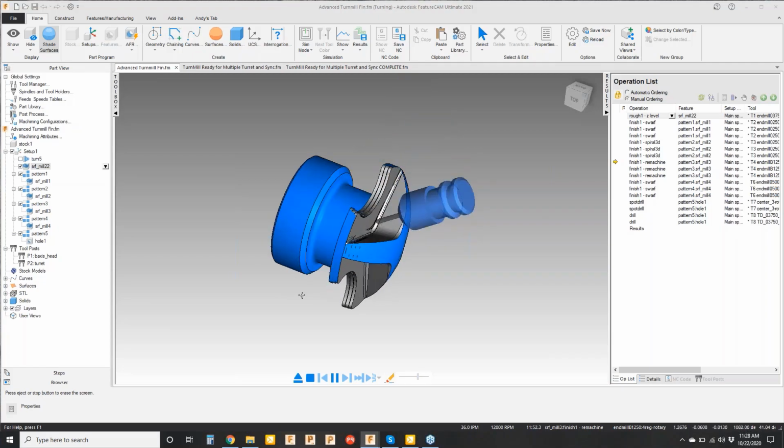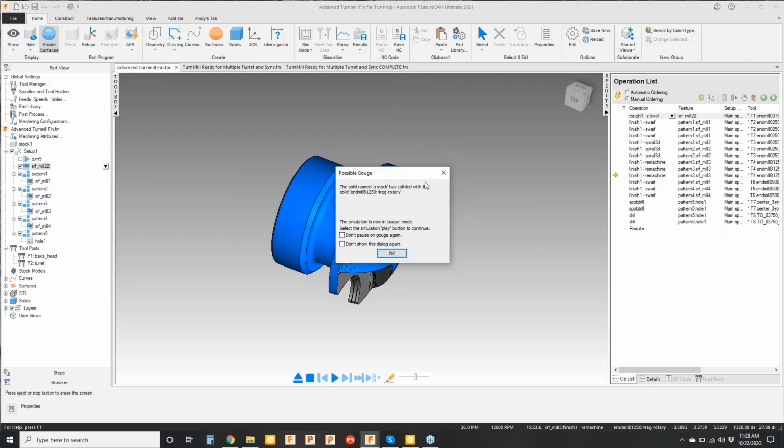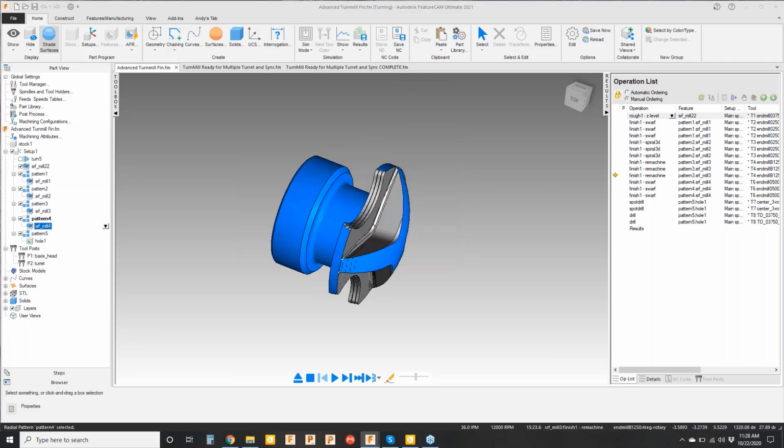And so you can just imagine if you needed to do something like this, how basic your hand-coded toolpath would be. And obviously with the CAM software, you can do so much more and have so much more of a level of control over all this. We're getting towards the end of the remachining here, and then we'll see the swarf, and then I'm going to be done with this particular thing, and I'll go show you that C-axis checkbox, just how that works real quick. And then I'm going to turn over to Phil to talk about some other things. I'll be back later to talk about some synchronization in FeatureCAM as well. But can you just imagine trying to do something like that? We even gouge check if we have that issue, and so on and so forth.